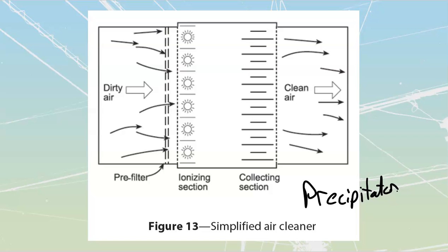What it does is it tries to remove dust and pollen and dander and things like that out of your air itself. And so we will take our air in. Over here we've got the dirty air that's going to be coming in. We are going to have a pre-filter just to take out the big chunks, the pieces of cat hair and things like that you don't want to necessarily run through here. That pre-filter section over here will just physically remove them. It's actual screening.